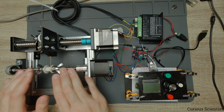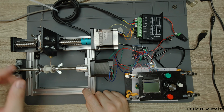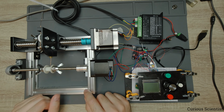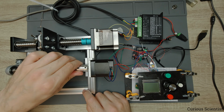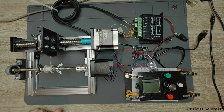And as I said, we have this 8 millimeter diameter threaded rod. Why threaded rod? Because then I can put the nuts on this with these wings, and I can fix the bobbin wherever I want, and it will not move. This gives the friction. I can center it, and it's very easy to remove it. So how I remove it is basically I just unscrew these 2 bolts, and then I just slide it out, and then I can remove it. It's like a 1-minute process.